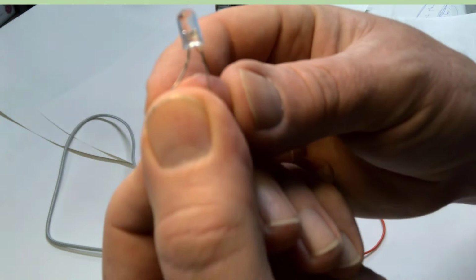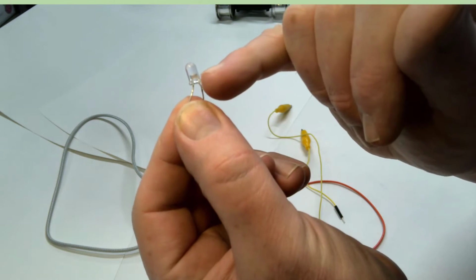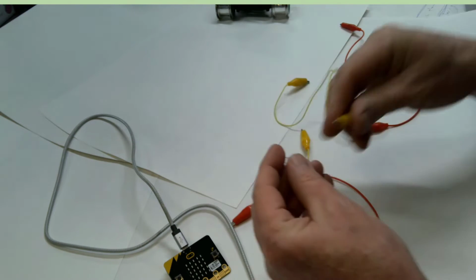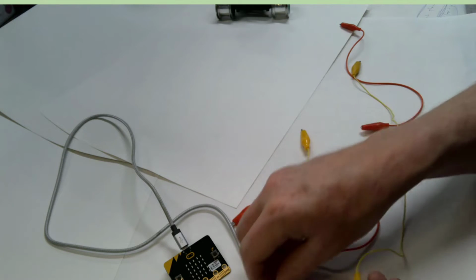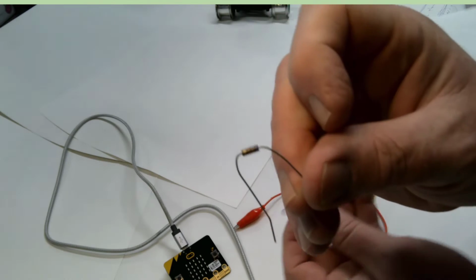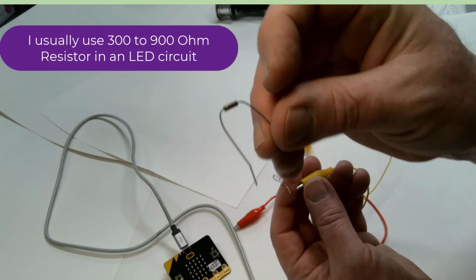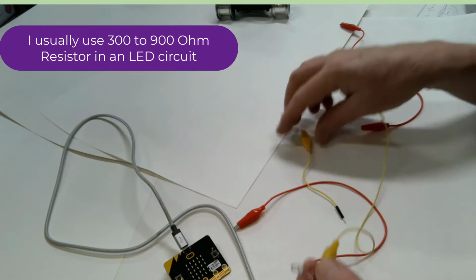Okay, so here's my LED, and I can see that this side looks like a small upside down L, so that's the one that points towards the negative voltage. And I have a resistor here that'll make sure the current slows down enough so that it doesn't blow up the LED or make it burn out.